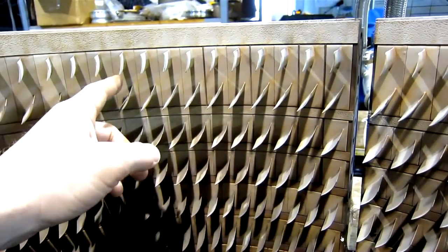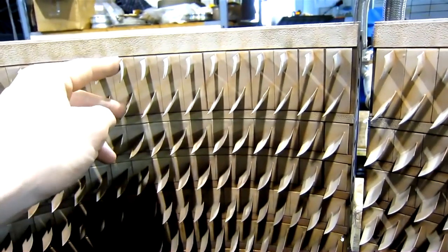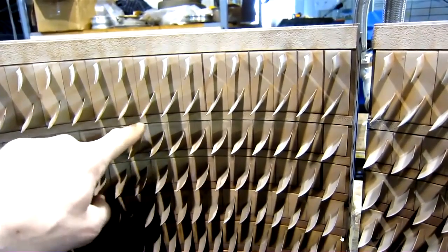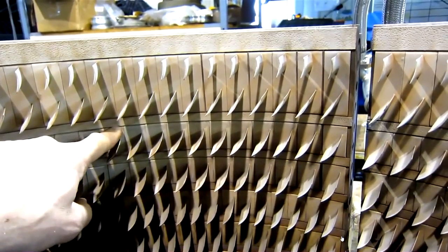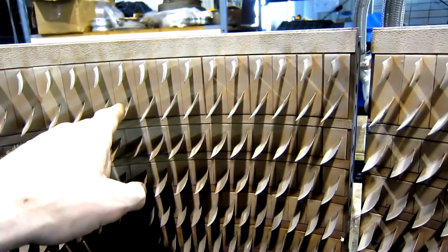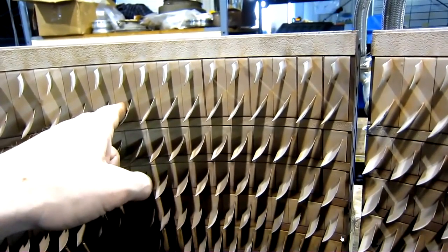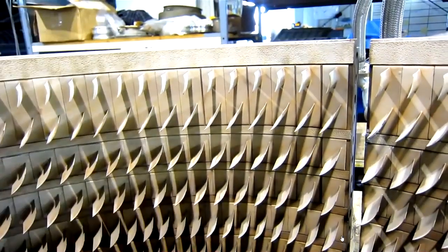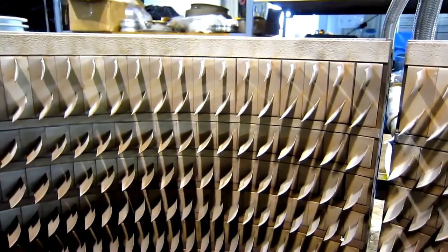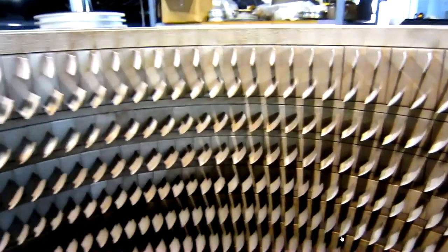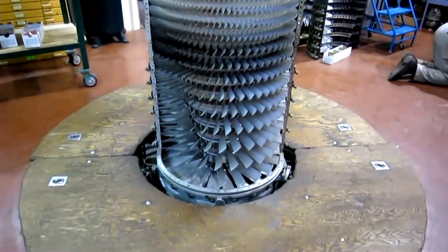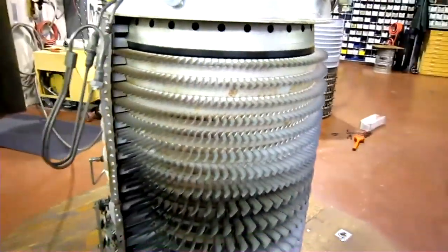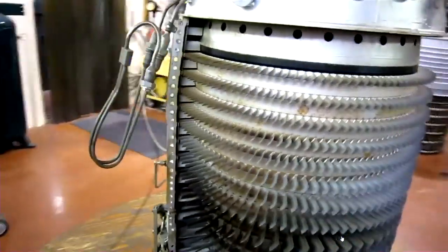Outlet guide vanes. This is a two-piece design. There's no rotor stage in there. The 17th stage of the rotor is here, and the air contacts this stage, or sub-stage, I guess, and then this one can be directed straight back into the diffuser, which we covered recently. Look at the way it looks with a case half off. Pop the hood, so to speak. Look at that. Look at all the stators lined up with the...